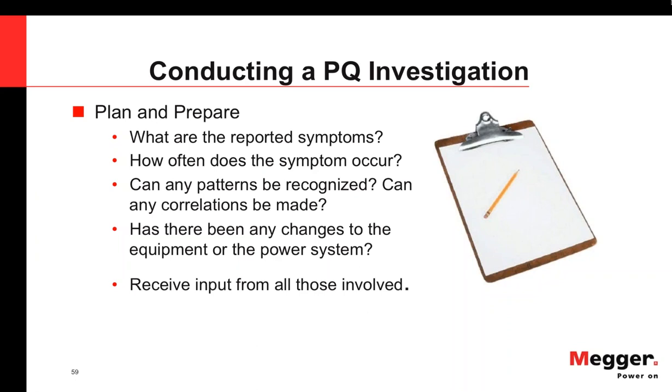All right. So with all that said, now let's go into how we actually conduct a power quality investigation to find out what the problem is. There are several steps that have to be followed. And one of the most important things is to plan and prepare for it. We need to ask questions when we're troubleshooting something. What is the reported symptom? How often does the symptom occur? Very important question, because this is going to define how long you're going to do a recording for.